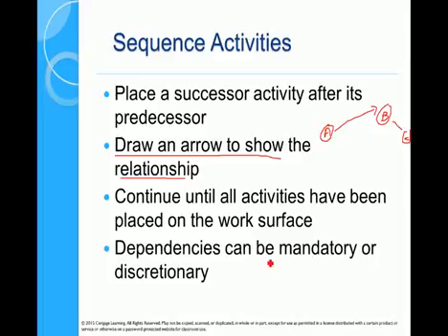These predecessor links can be mandatory. Things like logic, you can't put the ceiling on before the walls are in place. We cannot level the site until the soil test is done. That might be mandatory from a regulatory point of view. So mandatory mainly refers to this sort of relationship where the ceiling goes onto the walls. So the walls need to be there before the ceiling goes.